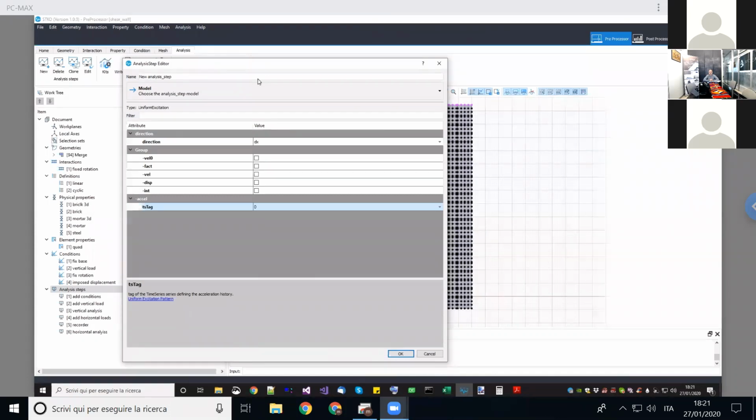Okay. So if you want to use it now, actually you have to use our own version of OpenSees. Otherwise, there is a quite similar constitutive model, which is the damage 2P. Unfortunately, it is quite similar, but it is not implex, so pay attention to the convergence issue.